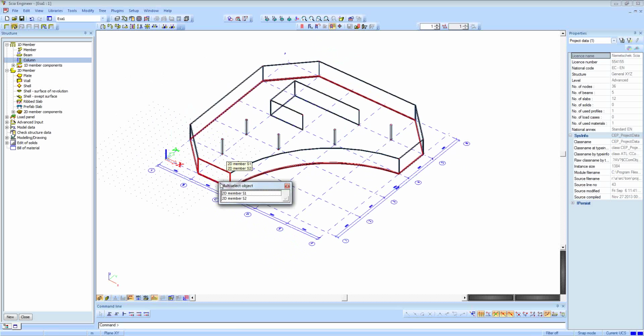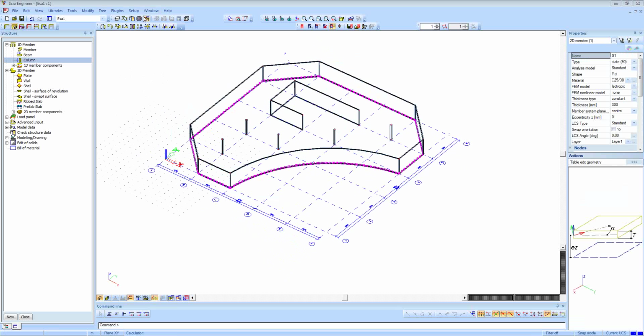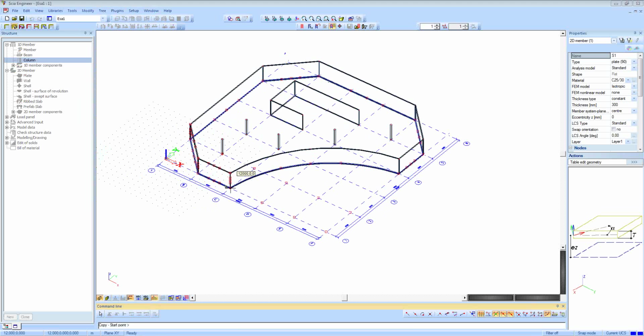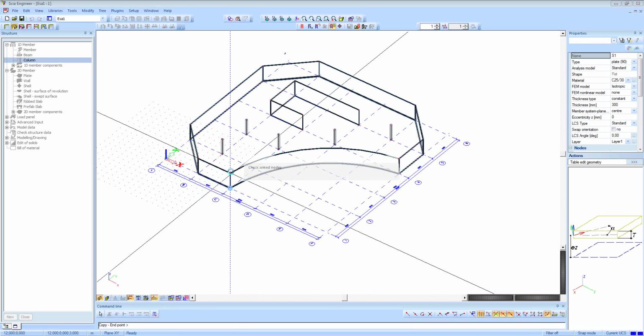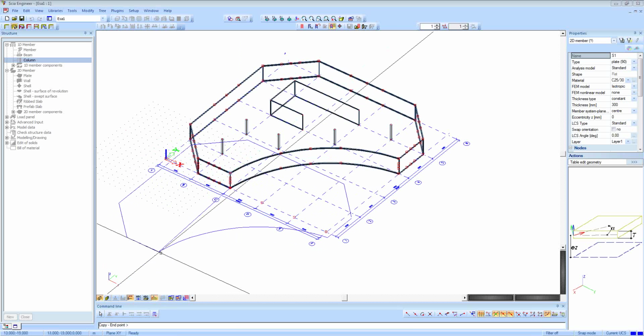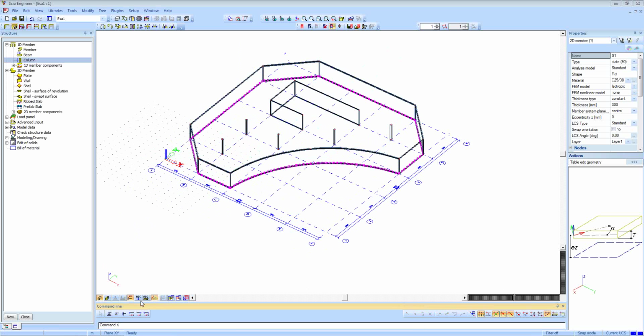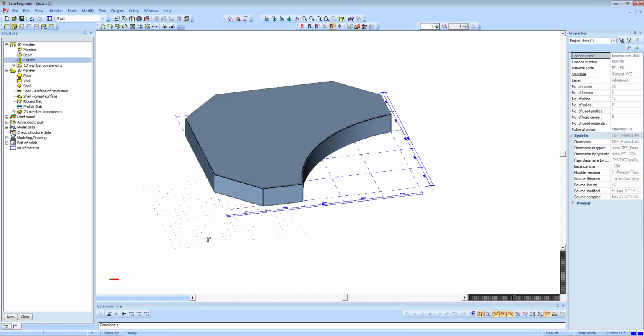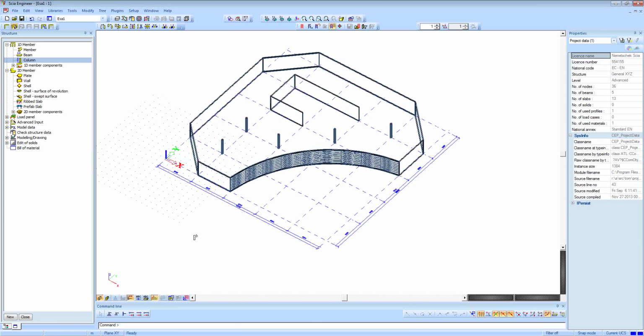To copy my first plate, my foundation plate, because the plate on the next floor is gonna be a bit similar, I'm gonna use the copy option. So under modify, I also have copy. And I'm gonna apply a vector, and then it's gonna use that translation to copy my foundation plate. See, I have copied the plate, and now, well, it's closed.